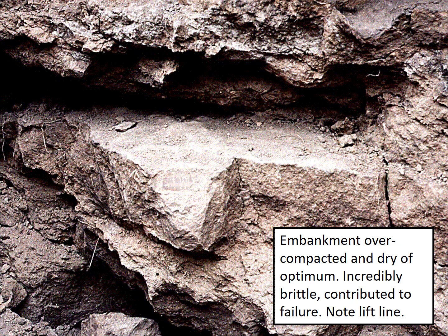The cause of failure was contributed to in part by overcompaction of a cohesive soil. It was overcompacted and dry of optimum, and it basically resulted in an incredibly brittle impervious core. There was some settlement and cracking, and then an internal erosion failure that happened at the dam.